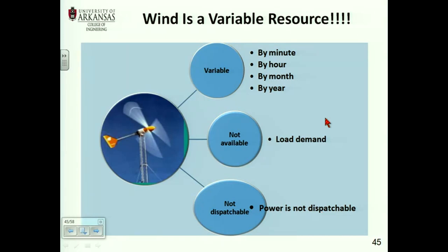And today we were talking about wind power. In an economic dispatch program, wind is considered as a negative load. Remember, input power is equal to what? Output power plus the losses. Reactive power, Q source, equals Q load plus whatever you have in the lines. Wind is considered as a negative load. It's on the right-hand side of the equation, but with a minus sign.